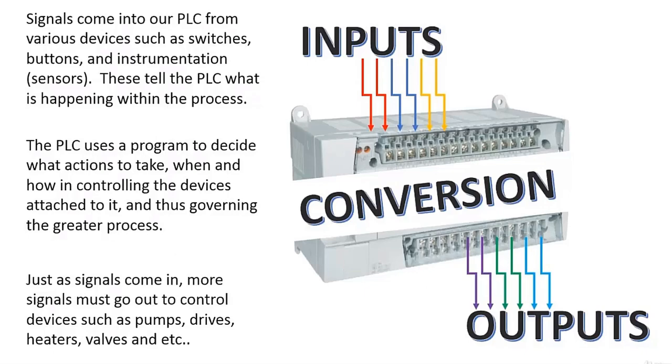This is section 3, and we're going to be discussing I/O, which means inputs and outputs. When you think about the word PLC, which means Programmable Logic Controller, the name itself implies that we're going to be controlling something. The signals that our PLC sends out to control devices such as pumps and motors and valves are called outputs. The signals coming into our PLC, which tell it what's happening in the process around it, are